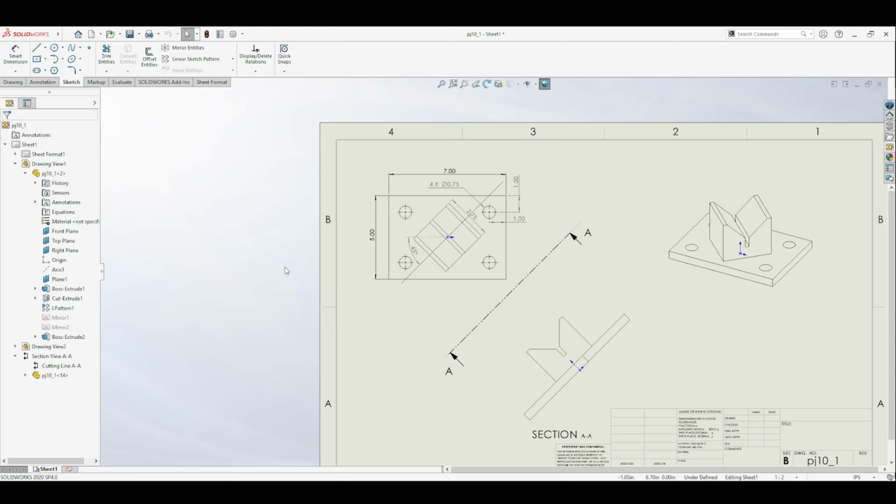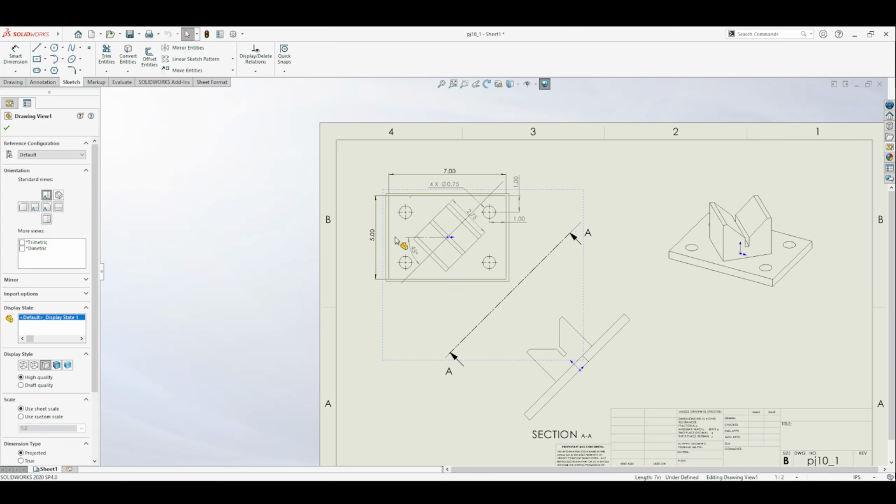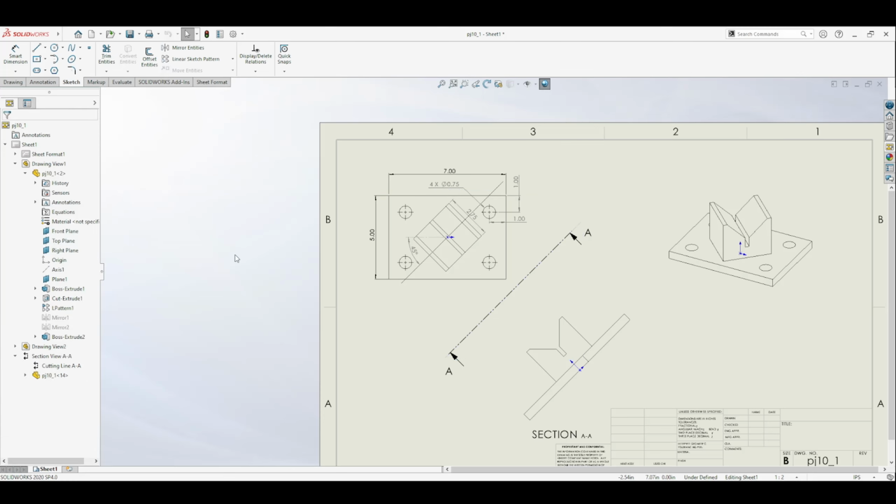Sectional views are great for looking at like a cutaway. If you have internal features, if it's a cylinder or some gadget, some part that has internal features, sectional views are great to show those, especially if they're hidden or they can't be seen really well. Like if you were to select this part and then you just show the hidden lines, obviously they wouldn't show really well from this view. A sectional view would do that really well. It would show it really well.